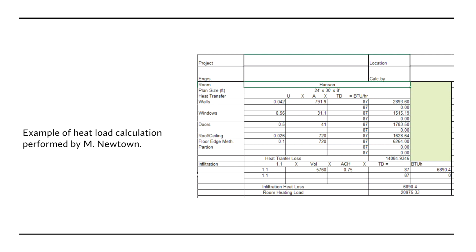This was an insulated slab on grade, and we are accounting for the insulation around the concrete floor that was in there. Okay. Anyways, when we get all done, we get our total heat load, and that's the number we're designing to. So, cool thing, 20,000 is a little over a ton. Well, not a little over. It's almost 2 ton, but a ton is 12,000 BTUs per hour, and this one's 20,000. Okay.